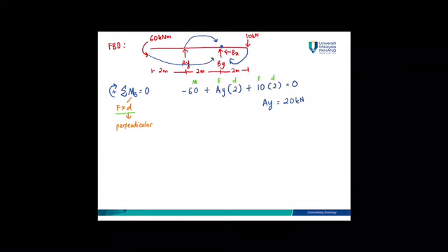After you get the AY value, then another equilibrium equation is summation of Fy. Summation of Fy is equal to 0, my definition is upwards positive. Do we need to take the 60 kilonewton meter? No. Why? Because the unit for force is Newton or kilonewton. The unit for moment is Newton meter or kilonewton meter because force is kilonewton, distance is meter.